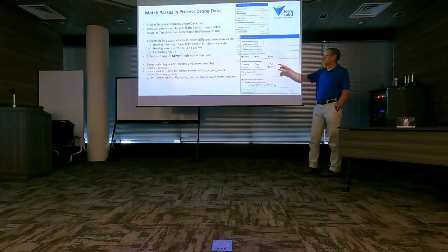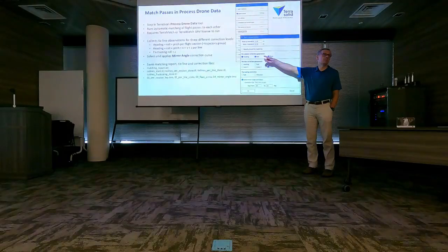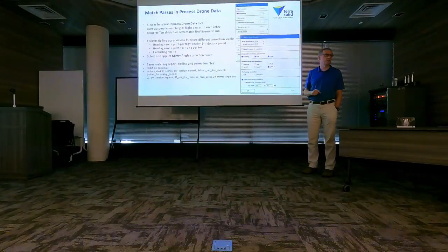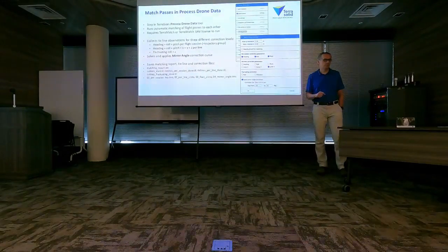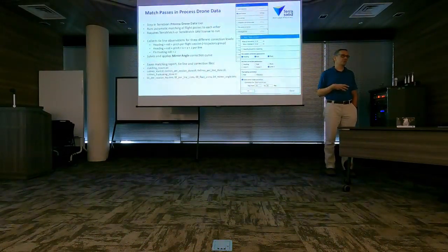So if I only do per session correction parameters, then I can have more vegetation without doing classify ground for matching. If I do per line correction parameters, then I have to think, is there some line in there which will be all or mostly vegetation?